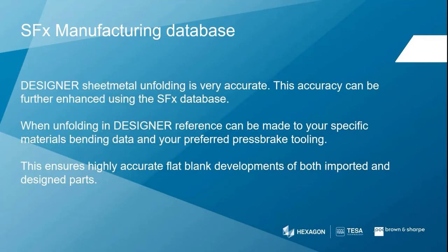Designer sheet metal unfolding is very accurate. This accuracy can be further enhanced by using the SFX database. When unfolding in Designer, reference can be made to your specific materials bending data and your preferred press brake tooling. This ensures highly accurate flat blank developments of both imported and designed parts.